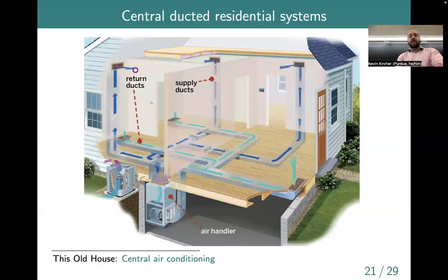But they blow cold air here, and hot air rises, so the cold air is going to sink. So having the supply high would basically promote mixing in the indoor air. And then we have all the floor ducts here that would suck back the return air. And then the outdoor unit would have the compressor. I actually don't know where the expansion valve lives, if it's indoors or outdoors. But it also would have the outdoor heat exchangers.